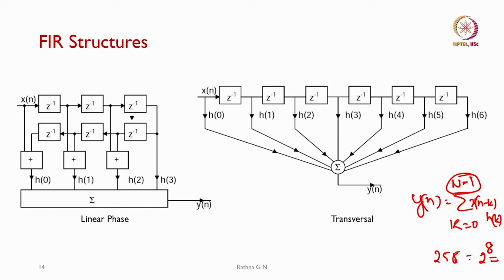So, if our adder is adding 16 plus 16 bit, or our registers are 32 bit, I can allow an overflow of 8 more bits, that is 32 plus 8. We call these the guard bits in our accumulator. We call it a guard bit in our DSP processors to take care of 40 bit addition.